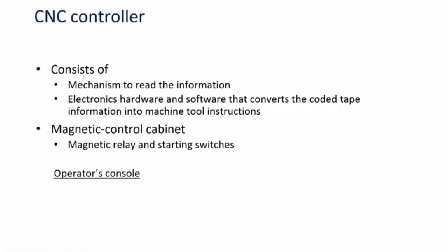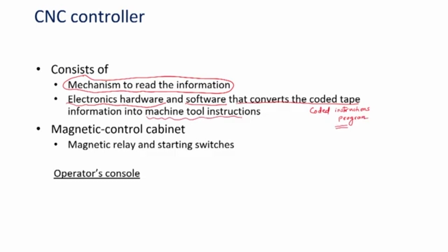A typical display or a GUI is there in front of you. So, this is the graphical user interface. It has a keypad, so you can see here a lot of keys are provided. The address keyboard, the numeric keyboard, then there are a lot of edit keys. This is the CRT display screen, various function keys are there, and all these keys are to be utilized to control the operations of the machine tool.